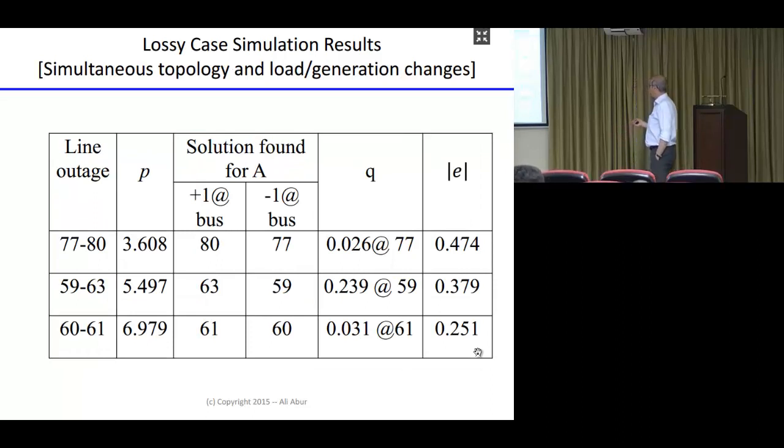And then now, if you further go and introduce slowly changing loads or generation, which is the more realistic case in an actual setting, then you also see errors. So here we notice that in addition to these, we also get errors because the remaining variables in X are not going to be exactly 0 because there are some load changes. Therefore, you see these small changes in injections in every bus. But those injections we assume to be small compared to the outage line.